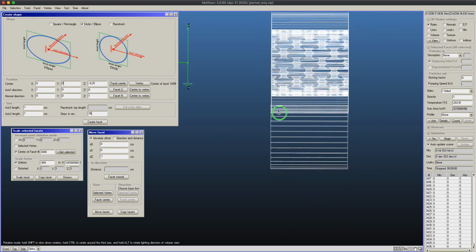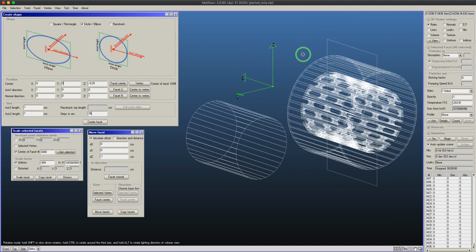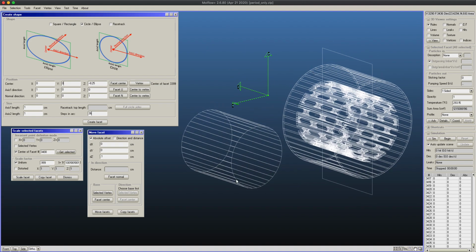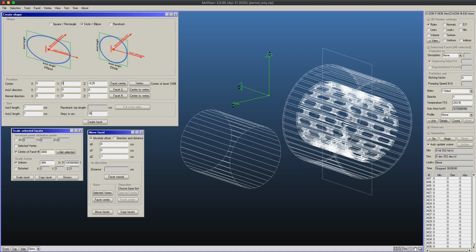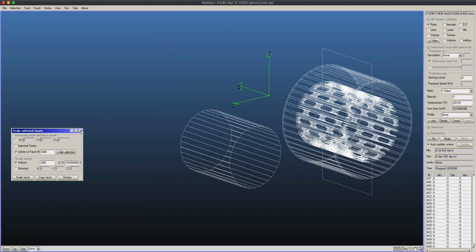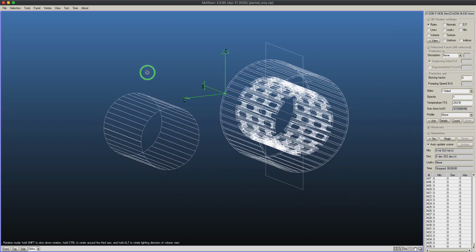All right. So the question is that you have to do calculations how transparent this should be to correspond to this. If you're using a CAD program, you can just automatically select the inner side, and your CAD program will tell you automatically its area. Then you can compare it to a cylinder, and then you exactly know the surface ratio between the complete cylinder and the whole cylinder. Since I don't want this tutorial to be dependent on an external program, I will do the calculation in Molflow. In advance, I'm telling that this takes some time, but the second time you do it, it will be much faster.